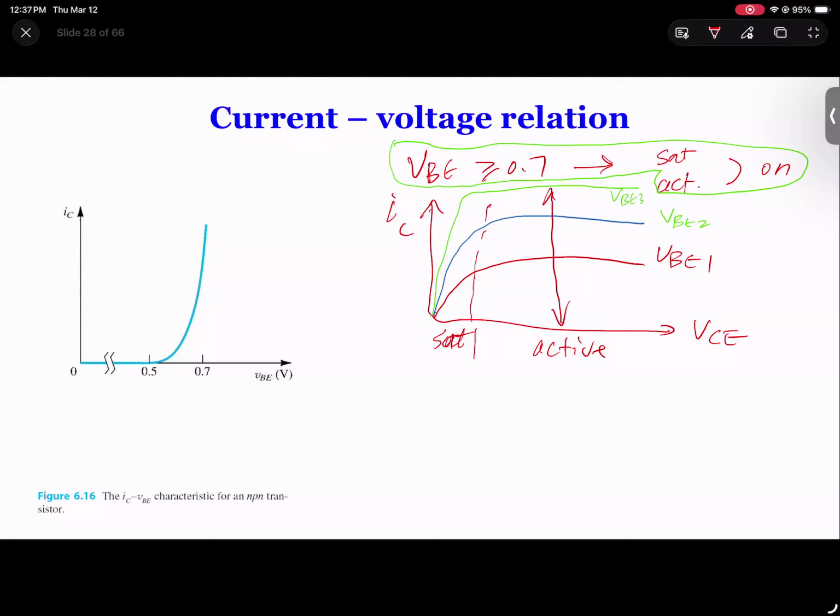We say, okay, if VBE is 0, then as VBE increases, IC increases, right? So we get the cross point at each point, and we get a current, and then we translate to this diagram. So now I'm going to draw IC as a function of VBE. Apparently when VBE is 0, the current is close to 0, and when VBE increases,